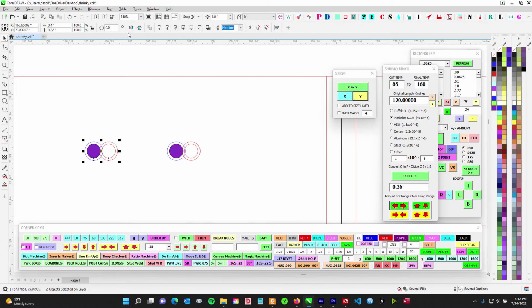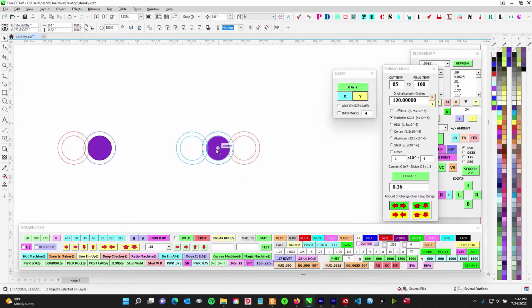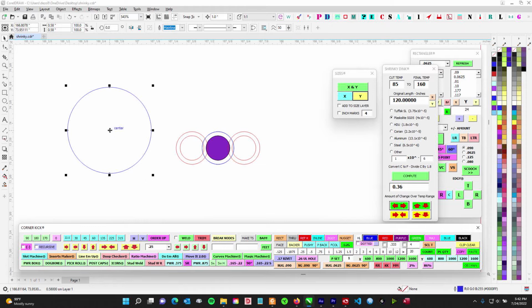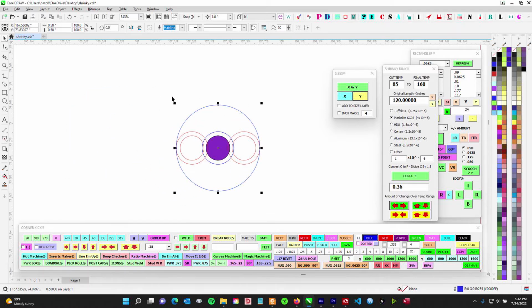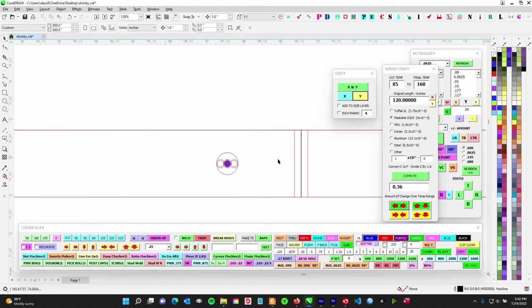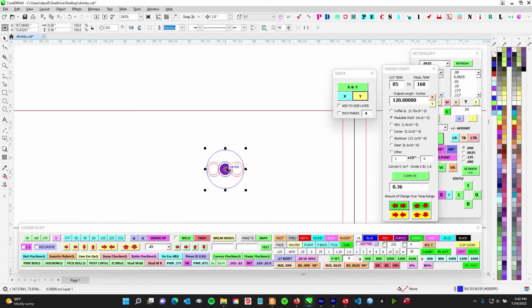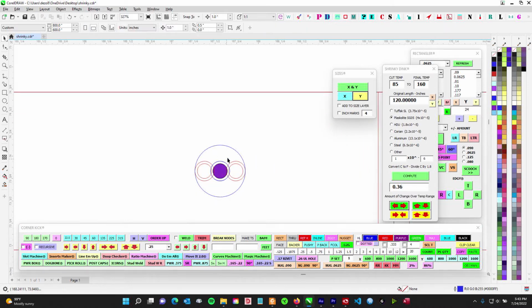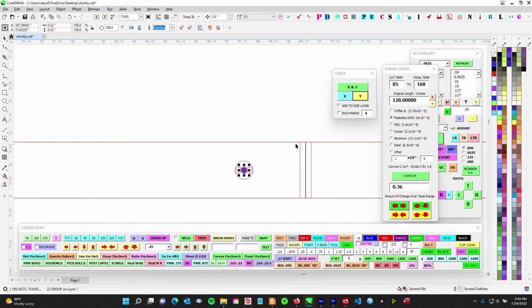So what I'm saying here is you could actually use this as a way of knowing how big a hole to drill. I just hit a button here that does it for me. But this is a 0.58 hole. So if you really want to give this thing room, you would essentially drill a 1/2 inch hole and fill it with silicone and allow this to be sort of like a bushing. And then this would be your 10-24 stud. And then theoretically, it would allow this thing to do its movement. That's one thing to think of.